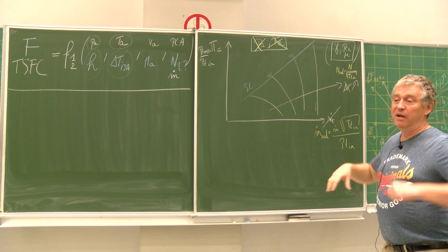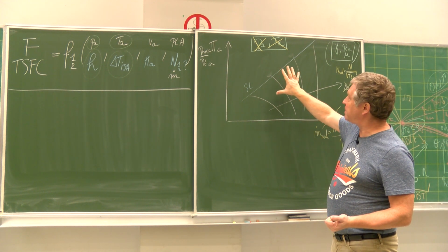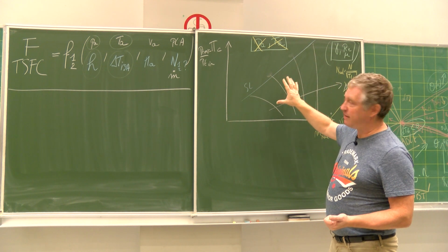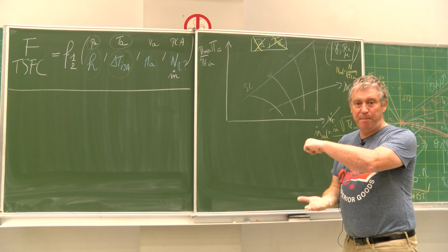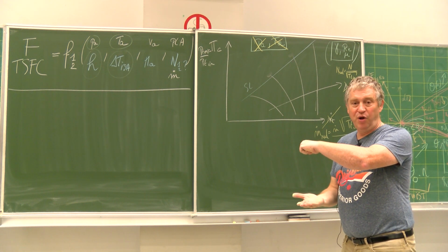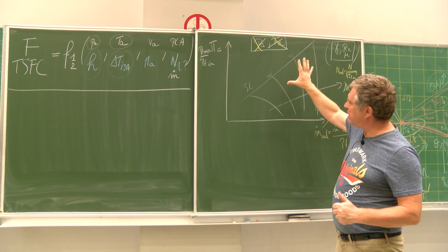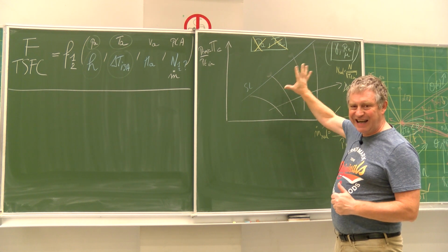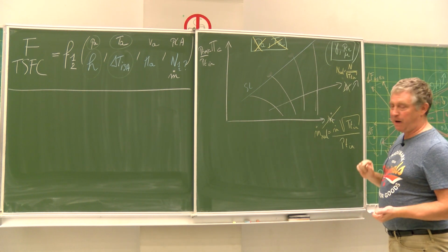And from a situation where you have a book of compressor maps, each sheet at a different couple PA-TA, you are coming from a book with I don't know how many sheets to one sheet. Just one sheet, which is one single compressor map with this parameter and this parameter.